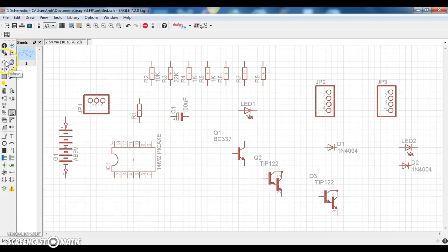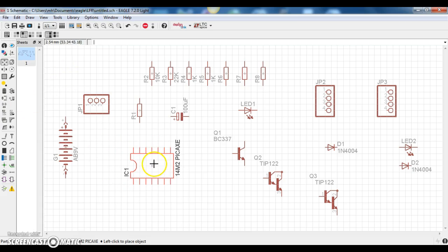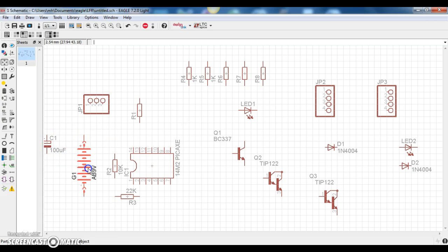You can rearrange this by moving the components around. So that's my way of rearranging. You could choose. There's no right, no wrong way, basically, except for the capacitor. Make sure that the capacitor is facing positive up, and so is your battery tray facing up.